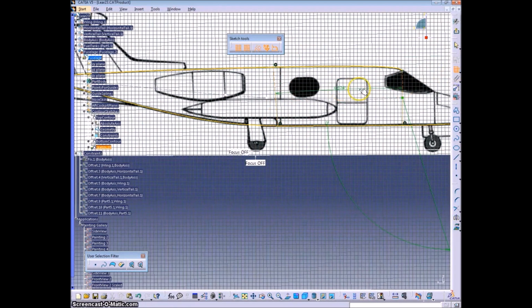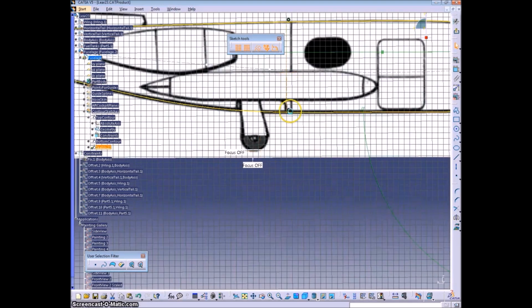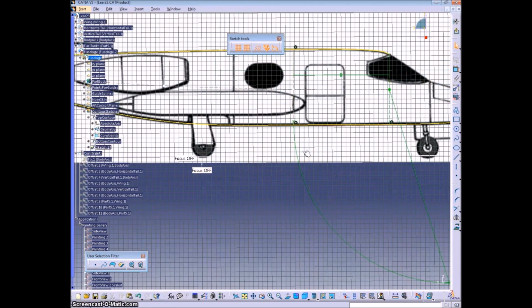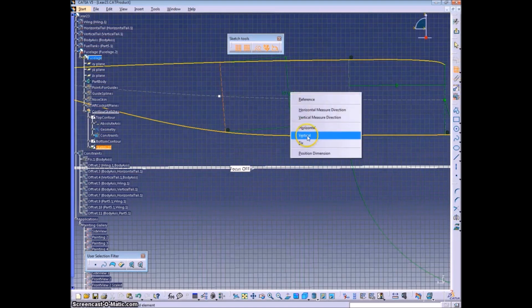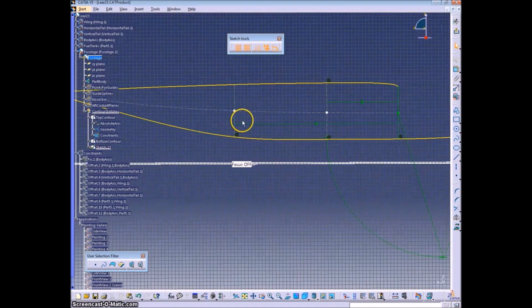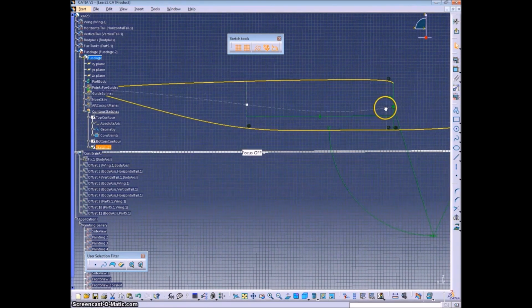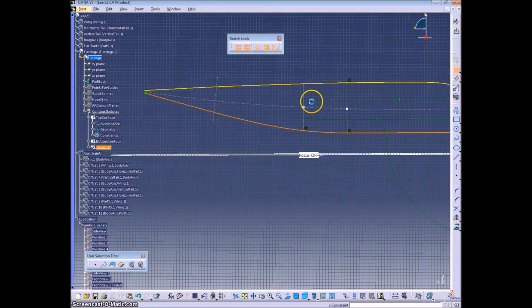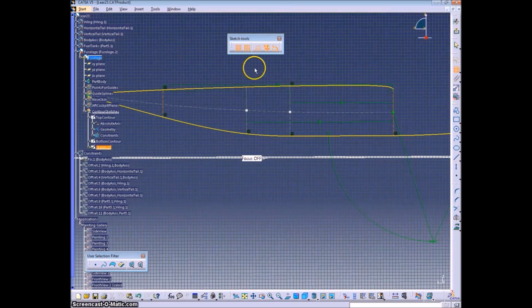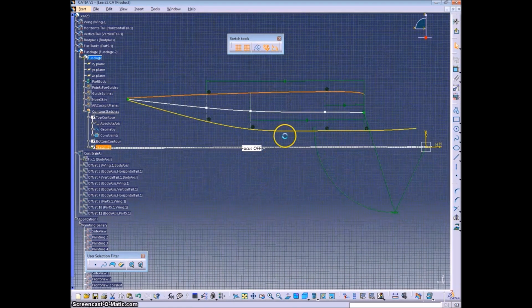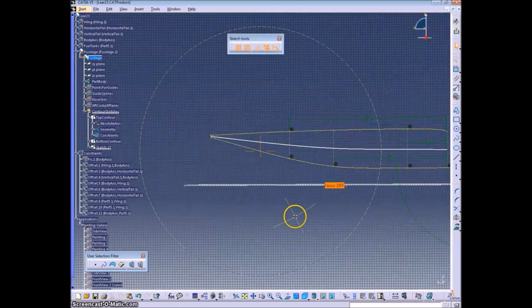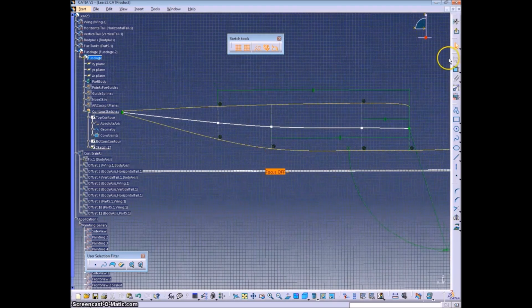Add in more vertical lines, one for each control point of the spline. Hide the sketch there so we can see what's going on. In the end, we want to be able to move these lines back and forth and not see any changes in the spline. So we're constraining each of these control points to the midpoint of the line. Then unconstruction object it. And there we go.